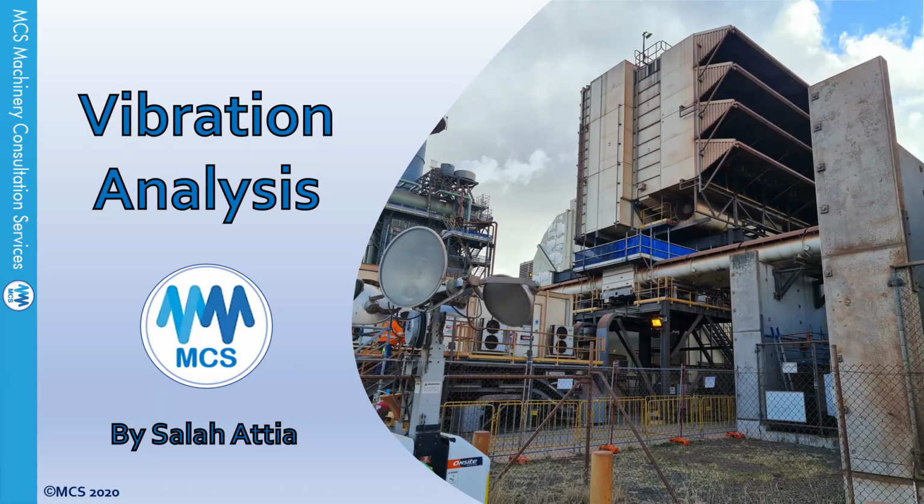Very good. With unbalance, as unbalance is a centrifugal radial force, you will see high vibration in both the horizontal and vertical directions. Because the horizontal direction has less stiffness, the effect of unbalance in the horizontal direction will be higher. That's why we see higher vibration in the horizontal direction than the vertical direction, but the difference in amplitude will be twice to a maximum of triple. Because of that, you can say we have an unbalance problem.